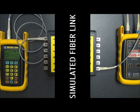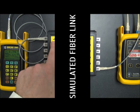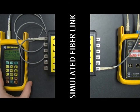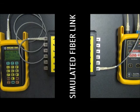Now, one thing to note here, notice that your fiber number went back to fiber number 1. The micro OWL conveniently sets this back to 1 because you want your 850 nanometer reading to show up with your 1300 nanometer reading for port number 1 for this link. So it automatically starts over at 1 again. Okay, so now again I'm going to speed this process up and we're going to store all 6 readings.